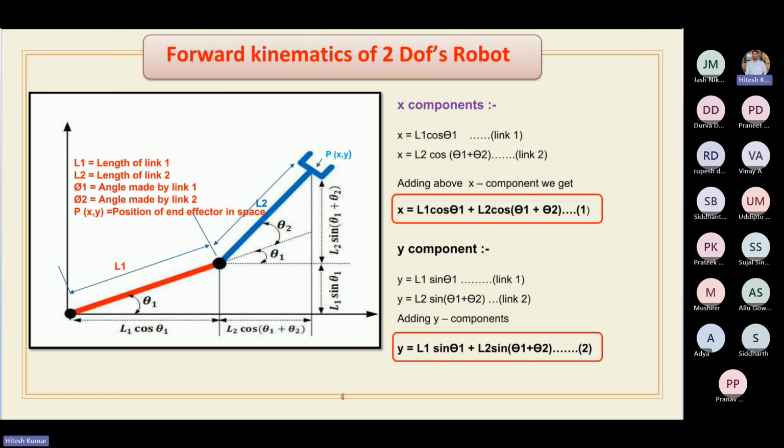So what was here in this? This is a 2D robot. This is a serial chain, all connected in series. We calculate the projection using simple projection. In a right-angle triangle, the base will be L1 cos theta and the height will be L1 sin theta. We add those and get the X, Y, and Z values. This is given in 2D; if the robot is in 3D, we will take that later in the session. This is how we calculate for 2D, and similarly for 3D it is very simple.